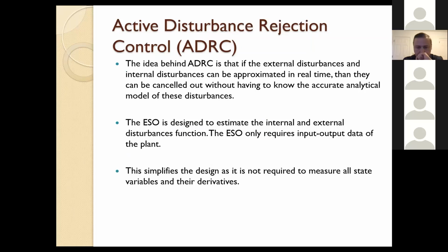The idea behind ADRC is that if the external and internal disturbances can be approximated in real time, then they can be cancelled out without having to know the accurate analytical model of these disturbances. This is one of the key issues that made ADRC attractive to many researchers, because it's simpler in this aspect. We don't need to make an accurate analytical model for the disturbances that might take place in the car.